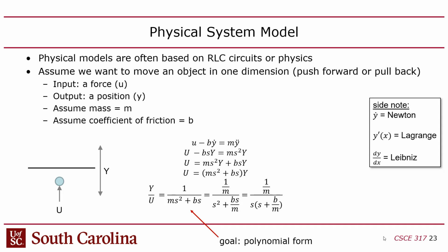Now again, that equation is kind of useless without doing something with it. So what I do with it is I convert it into a transfer function in the s domain, where y is the position and u is the force. So now I have a plant model for this coin. Now again, the goal is to do this for the cube. Can you do this for a cube? If we had the intellectual wherewithal, we'd figure this out, but we're still working on it. We'll get it. But we want to do a cube. This is a coin, same principle.